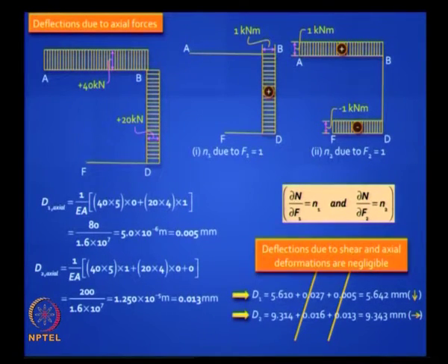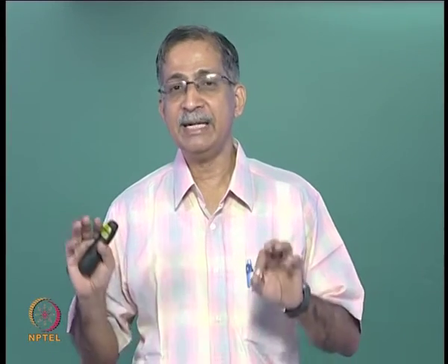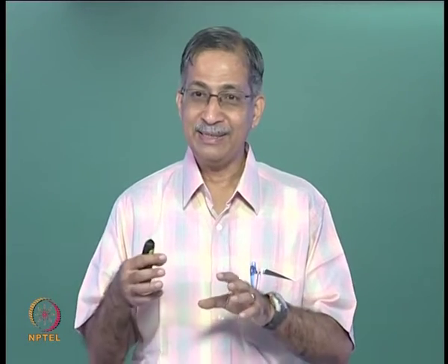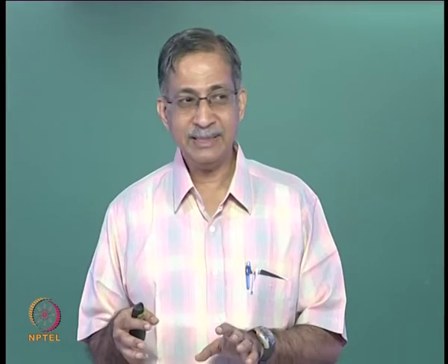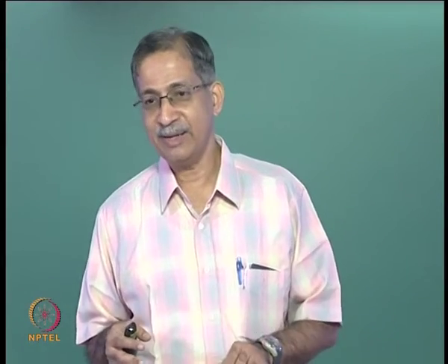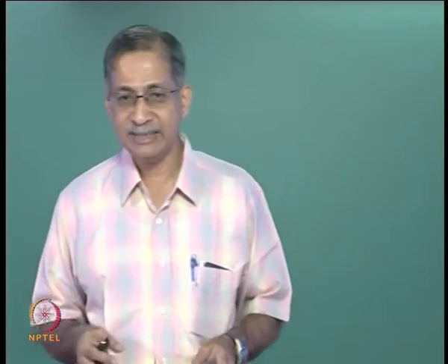So there is again another proof why we can ignore shear deformations and axial deformations in normal frames which are well proportioned. Earlier we said that the energy caused by shear and energy caused by axial forces is negligible. Now we are actually saying not just the energy, it is also the deflection. So do not bother, make your life easier.